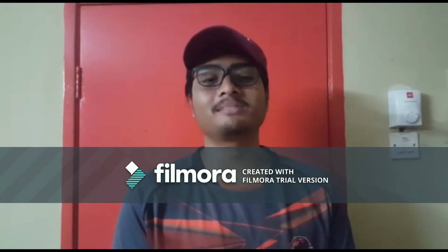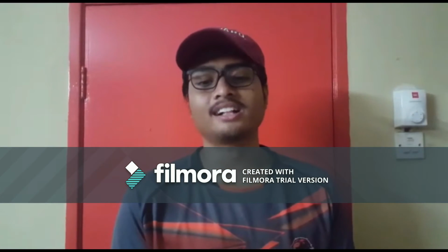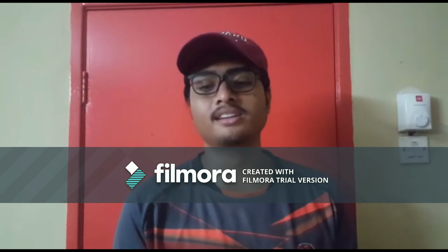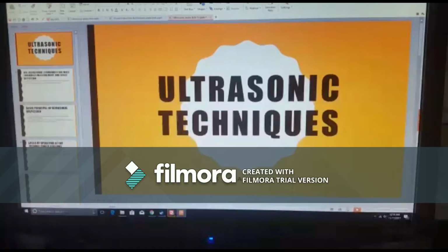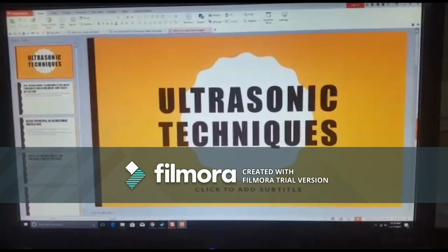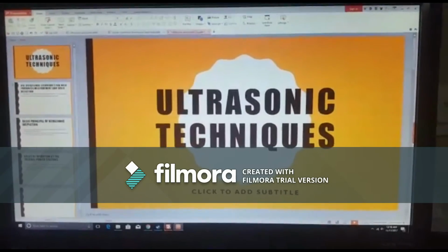My name is Muhammad Zikry bin Kamisan, and I suggest ultrasonic and visual inspection techniques as NDT applications in the thermal power plant. First of all, use the ultrasonic technique for wall thickness measurement and scale detection.